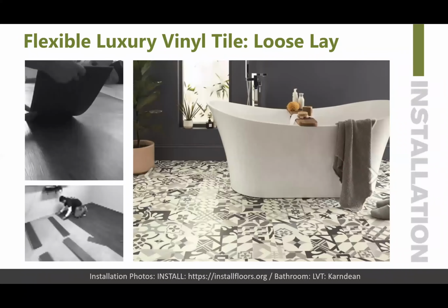For loose lay, flexible luxury vinyl tile can be installed over existing floor coverings, which is one of the advantages as well. Vinyl flooring is adhered to the edges of a subfloor, then additional planks and tiles are typically laid in place without an adhesive. Loose lay can easily be removed and replaced. This makes loose lay tile an ideal option for areas where flooring may be temporary or have a short lifespan. It allows you to do the replacements and will not damage the substrate, but also the flooring product. So you could reuse the flooring material.